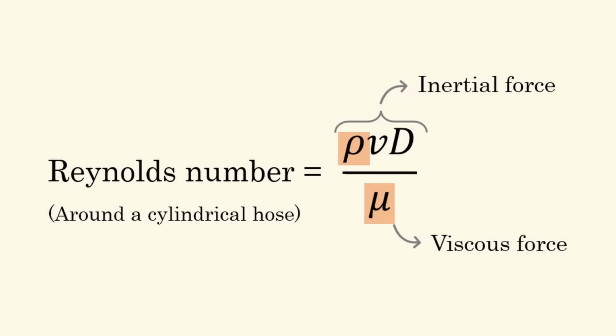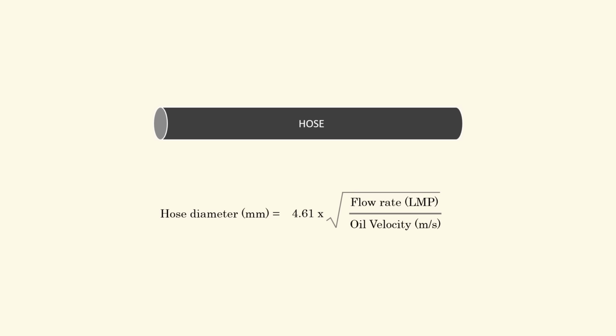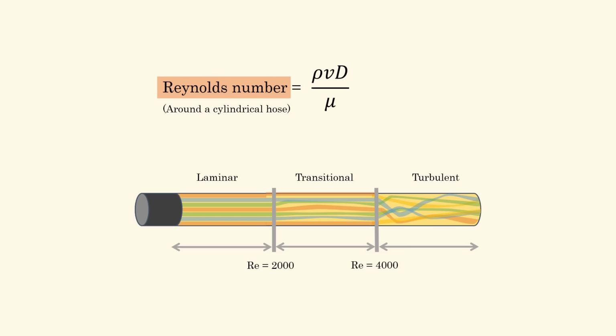And the hydraulic oil density and viscosity varies from one oil grade to another. So it is possible that at same velocity, in same size of hoses, one oil can be laminar and other can be turbulent. This is why even after sizing the hose using recommended velocity, we must check Reynolds number and ensure it remains below 2000 for a specific hydraulic oil being used.